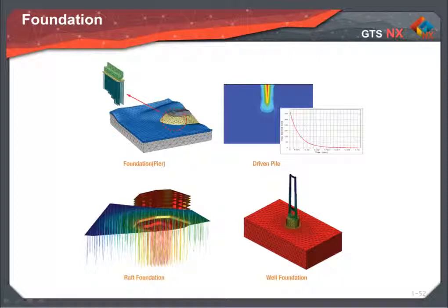When we're dealing with foundations, we can analyze driven or bored piles' behavior either in isolation or in grouped arrangements subjected to any combination of vertical, lateral and eccentric loads. We can estimate the bearing capacity of various types of foundations as well as differential settlement due to active load sets.